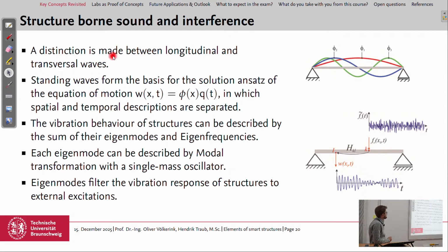Then today we started with structure-borne sound and interference. We made a distinction between longitudinal and transversal waves, and had this small experiment for longitudinal waves here in the lecture. And we got to know that standing waves form the basis of the solution ansatz with the separation ansatz, where we have the solution for the equation of motion consisting of two parts, the spatial and the temporal description. The vibration behavior of structures can then be described by the sum of their eigenmodes and eigenfrequencies.